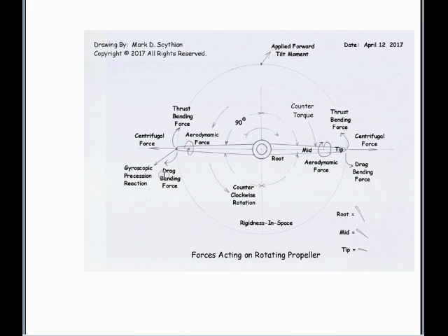So the precession is kind of something that is problematic and needs to be corrected on the airplane. The torque is not too bad on the airplane with the wings, but on a helicopter they take advantage of precession for steering, and on one end torque has to be canceled in the opposite of the rotor rotation direction, whereas it helps a little bit in the natural torque or counter torque reaction for steering on another axis or another direction of the yaw. Okay, so we got the helicopter, we got the airplane.